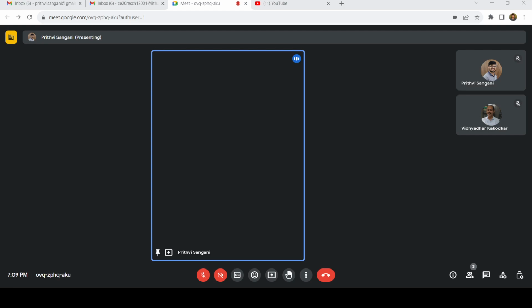So delta 1 plus delta 2 should be equal to 0: minus 676 by AE plus HC times 16 by AE should be 0. HC is going to be 676 divided by 16, that is 42.25 kilonewtons.